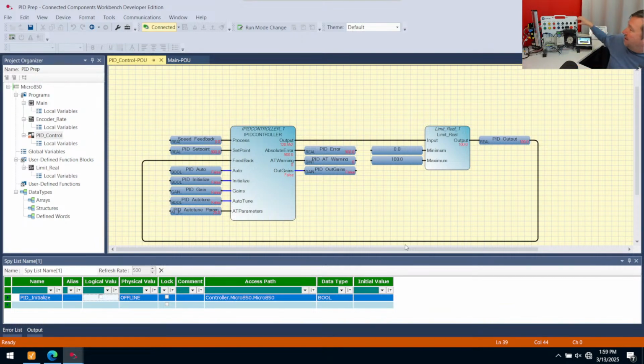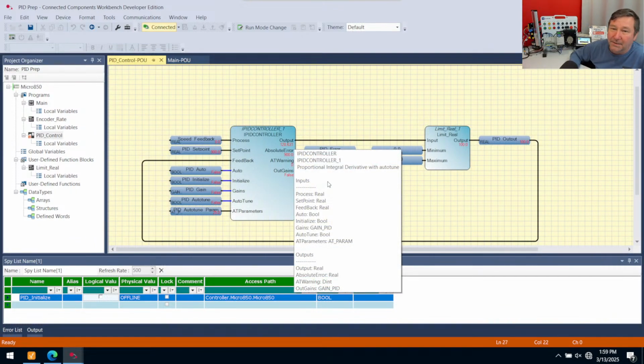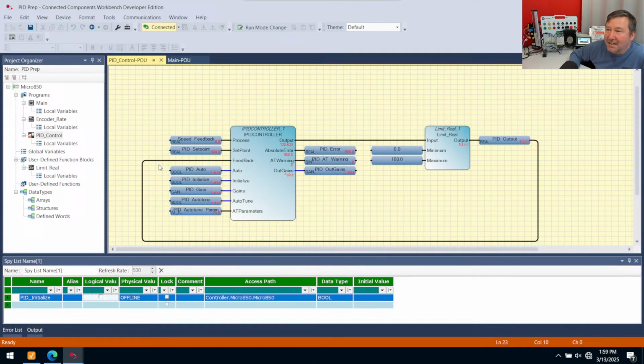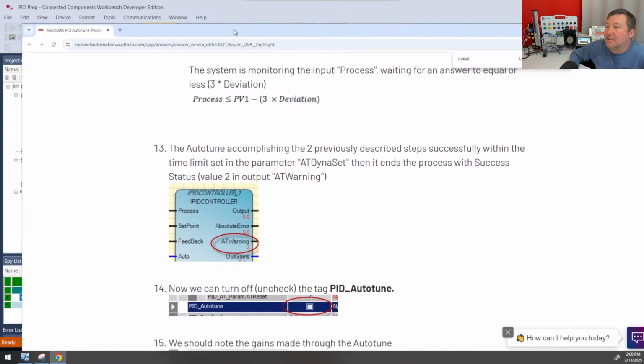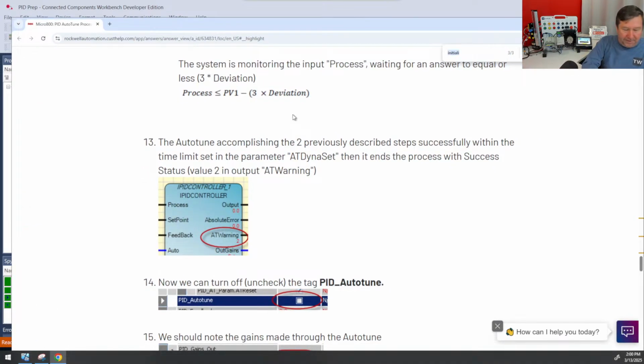So now when we try to switch our PID on, it's going to start off wide open. Now, there was a lot of documentation that is completely gibberish about how this PID auto works, but it does not do what you think it does, such as switching between an auto and a manual mode. In fact, if we look, let me search for auto.